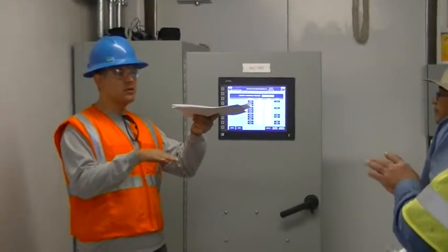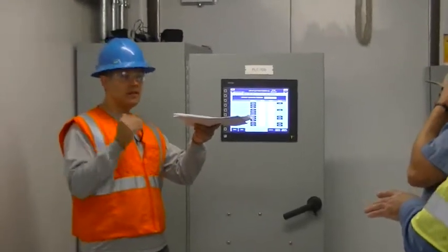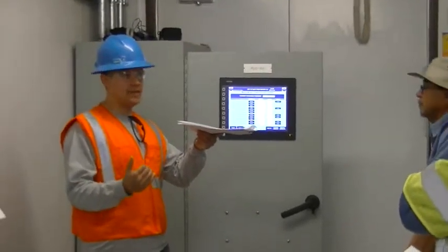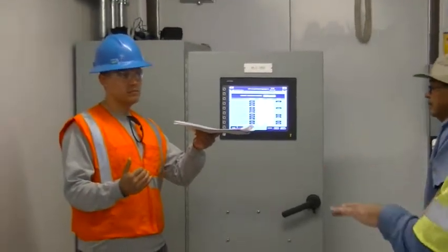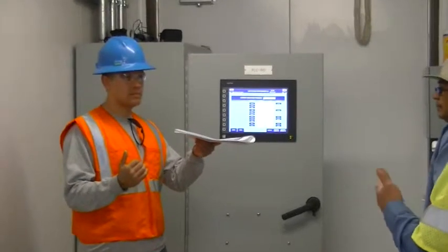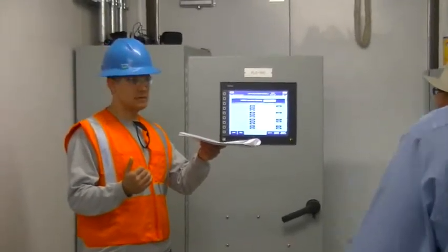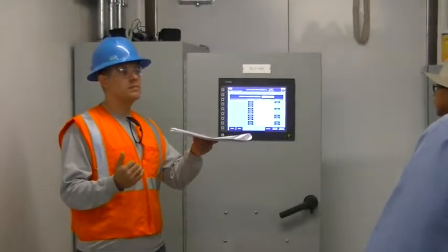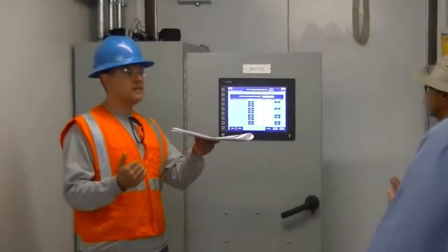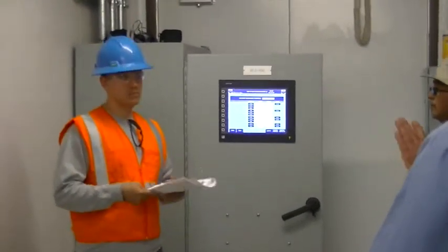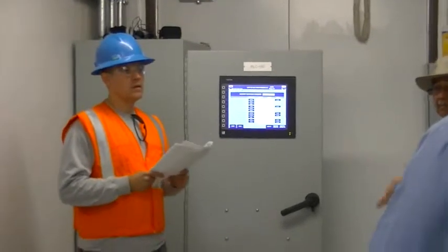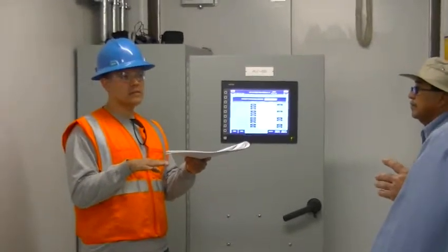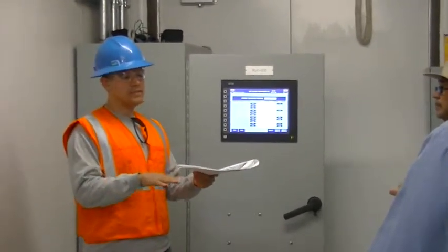Below 62, for what, a minute or so? For a minute. And that's if that other VFD's got to be at 100% during that time. Right, okay, and then the second one will kick on. Yep, after your minute delay or whatever. Correct. Both of them will ramp up, bring it up to 65 is what they're going. 65, okay, and then the lag pump kicks out once it's down.